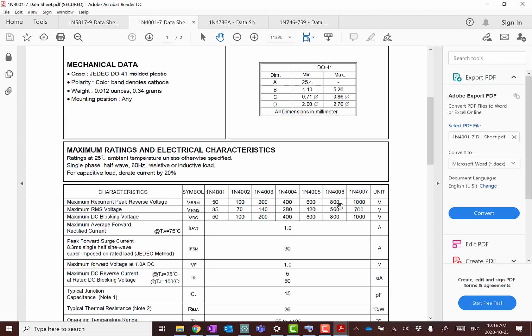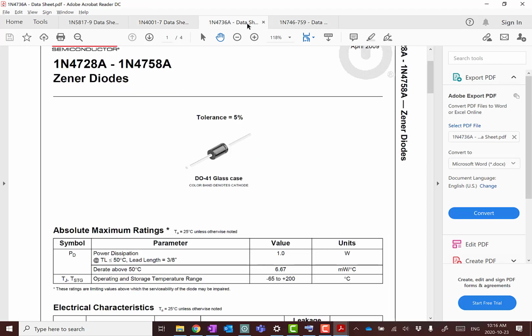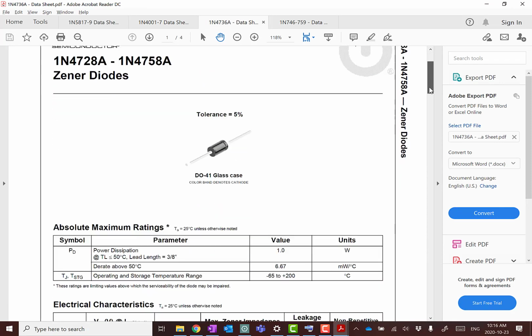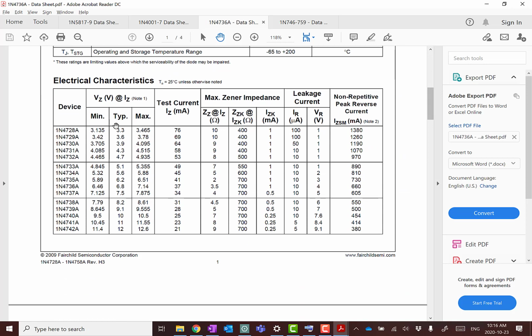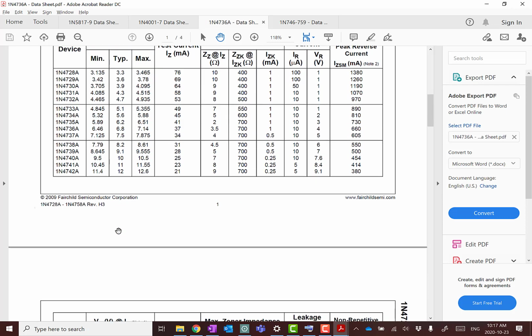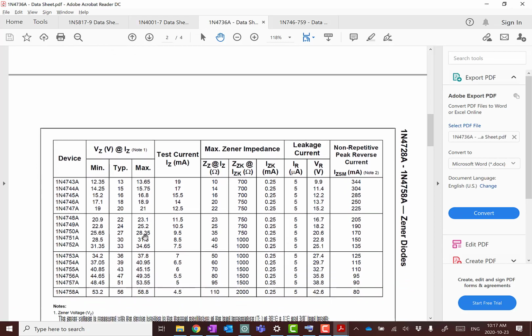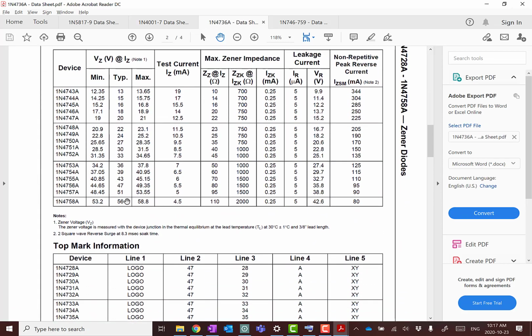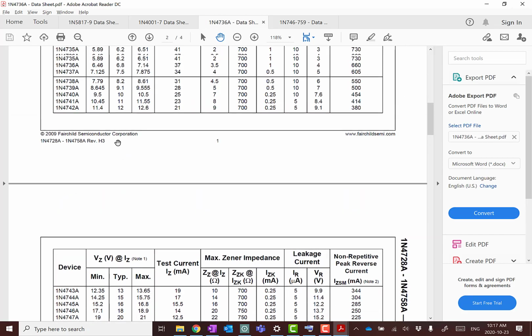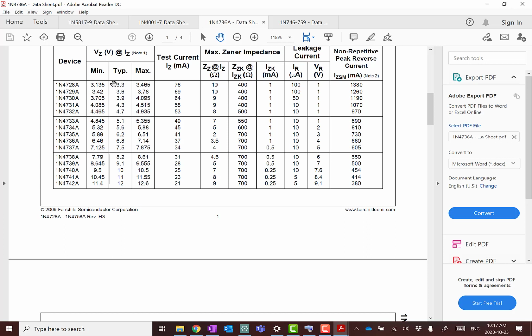So if we go back here and look at some Zener diodes, here's a series of Zener diodes, and we'll see over here in the columns on the left that you can get them for kind of any breakdown voltage that you choose. These ones go up to 56 volts of reverse breakdown for typical values, right?